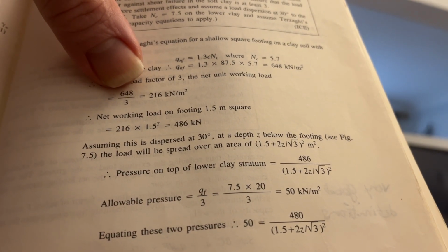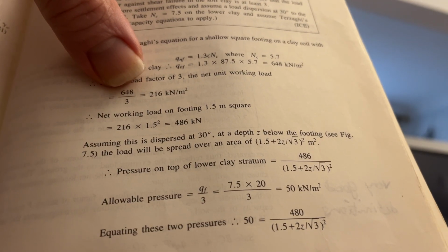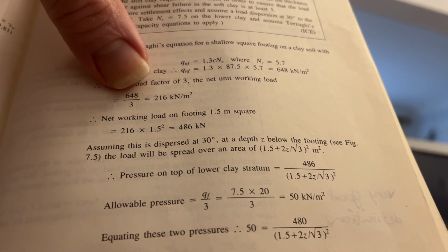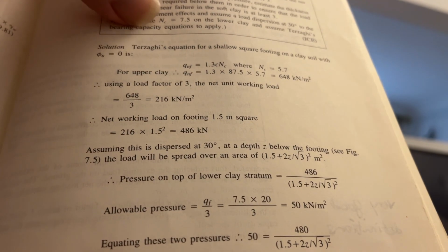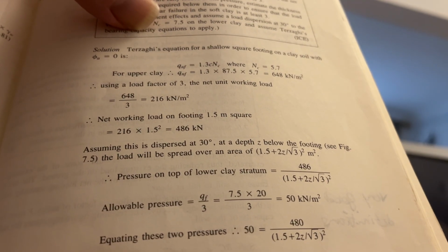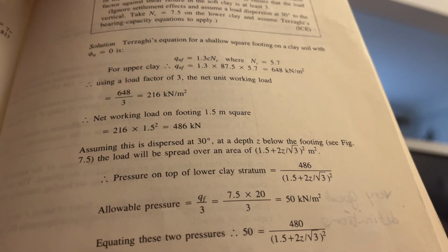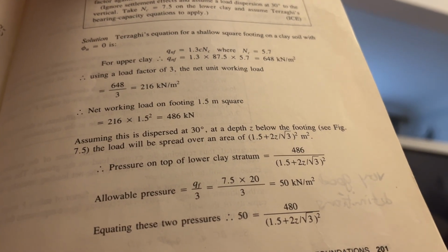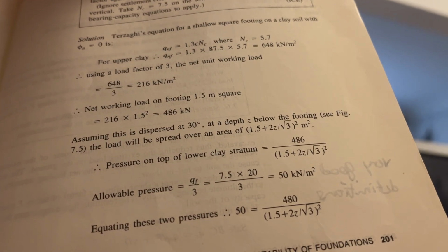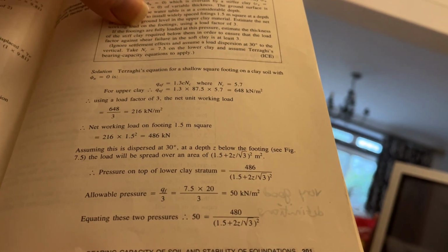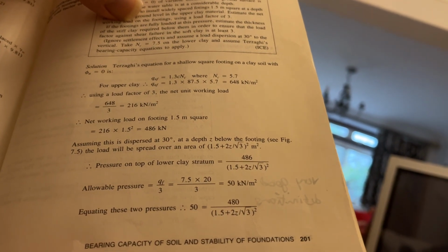Pressure on top of the lower clay is that. The allowable pressure is QF divided by the safety factor of 3. NC for the lower clay is 7.5, and the CU for the lower clay is 20. So that means it's 7.5 times 20 divided by 3 equals 50 kilonewton per meter squared. Equating these two pressures equals, oh right,